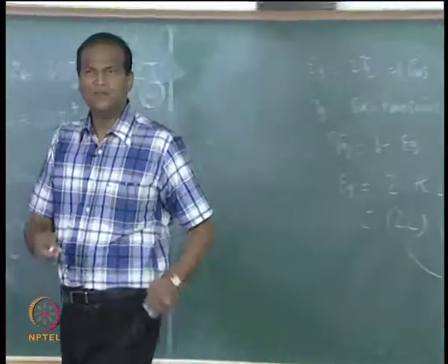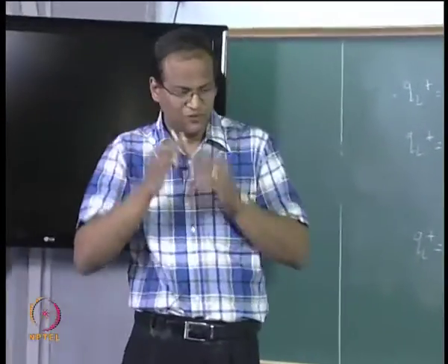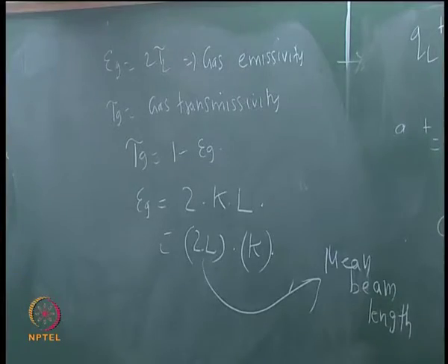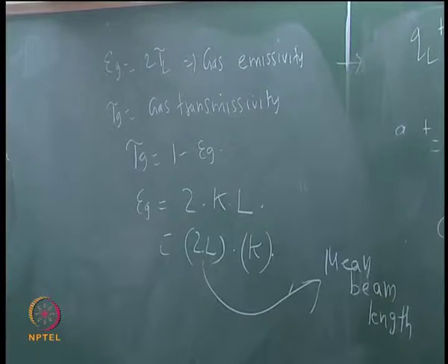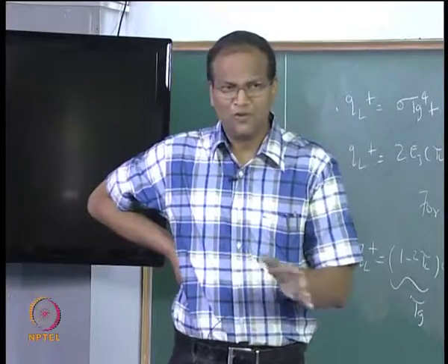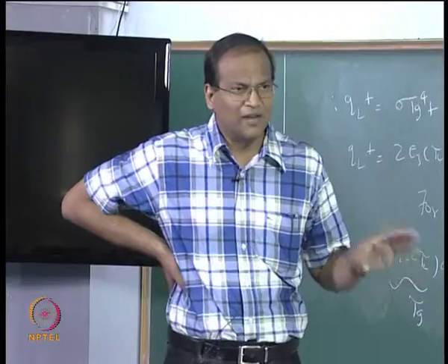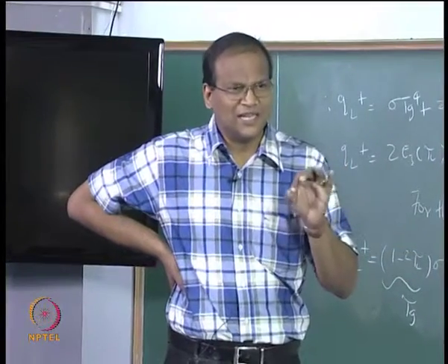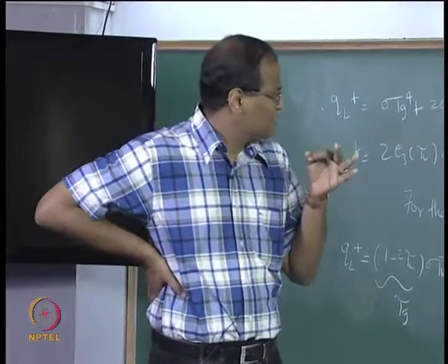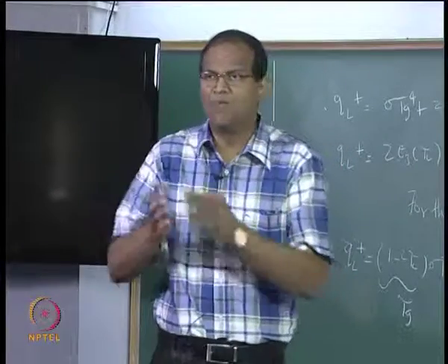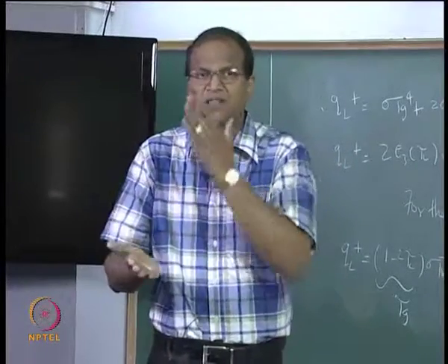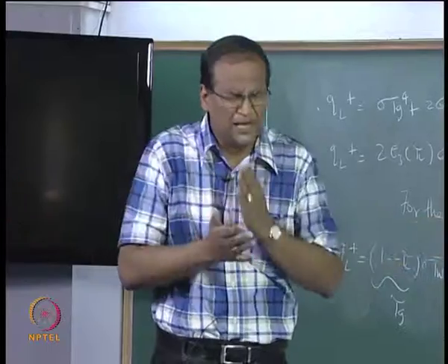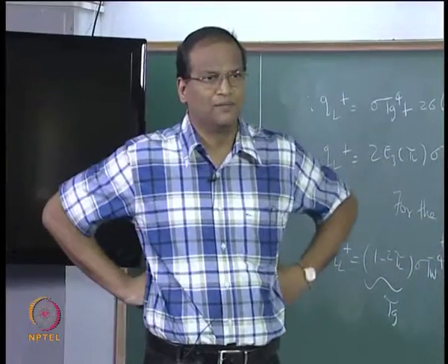So this is a terrific progress we have made in the last 50 minutes, that we started out with the equation of transfer and did all the mathematics, exponential integral, and optically thin gas and all that. We arrived at a stage where the gas emissivity can be composed into 2 distinct parts, and the thermal part can be completely separated from the geometric part.